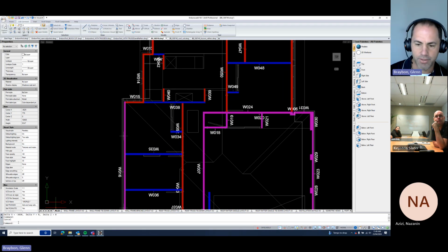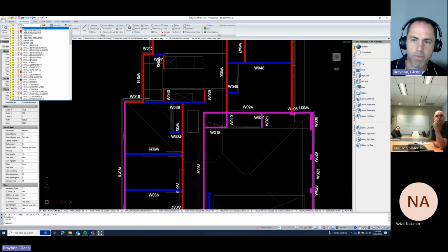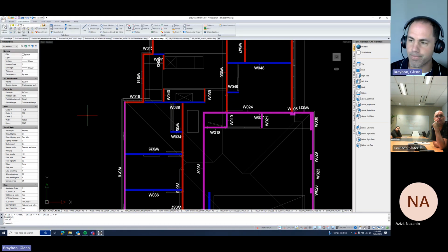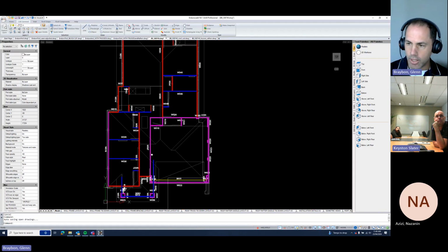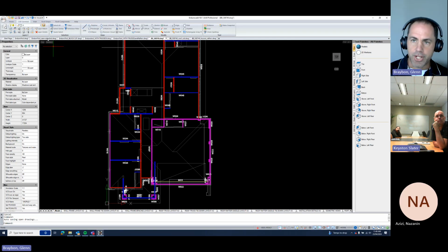Yeah, exactly right. Because it's the X plane, that's obviously horizontal. So if there are two different height walls, we're not clicking on a diagonal. We're clicking in that X, Y, and Z plane for the DIST. So I use the DIST a fair bit. Layers, sometimes you might want to turn on and off. If something doesn't want to be visible, you're probably better to use the visibility tab, but there are some options in there as well. So that's pretty straightforward.